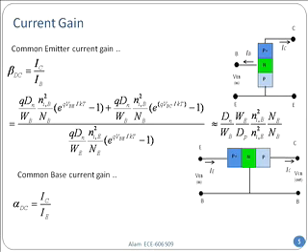IB is a tiny amount of current, but IC over IE, should that number be larger than or smaller than 1? The current is coming from the emitter and flowing in the collector, right? So it could be at most 1 and most likely less than 1 if there is any recombination and other things, less than 1. And also you can relate it to the beta DC, so you don't have to calculate them separately because of this.